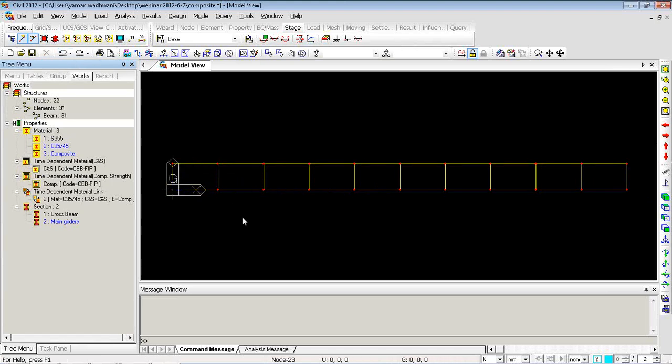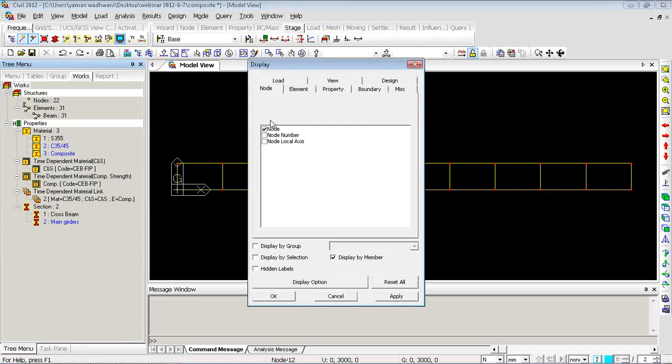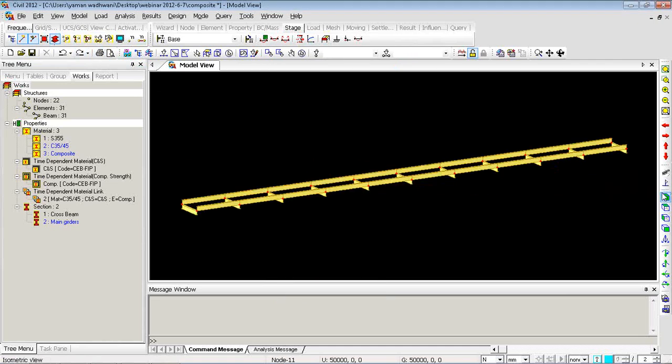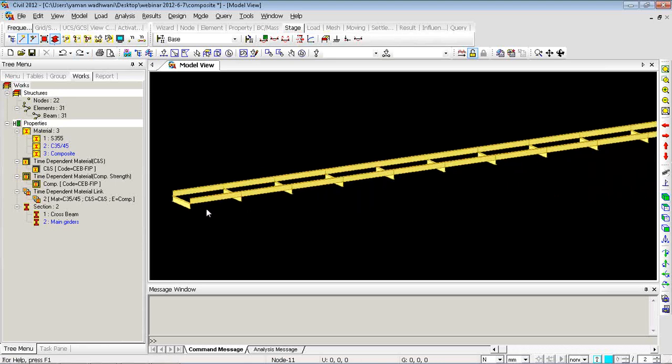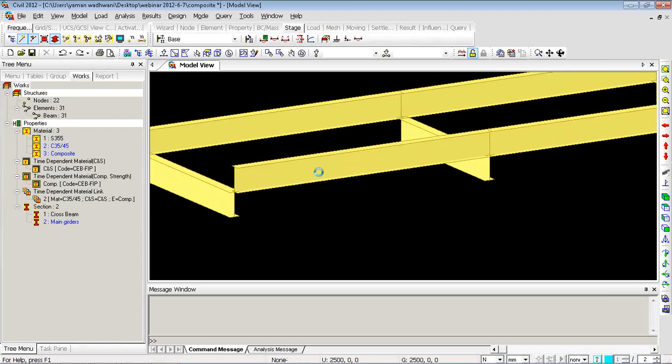I only want two girders, as I entered the section properties for two girders. This view, this XY, shows the global XY coordinates. Let's undisplay it for a better view. Okay, now it is clear. And switch on the 3D view like this. So here we can see the center bottom which we defined for the cross beams, these are all inputted as cross beam sections. So center bottom, you can see that the bottom is connected, or everywhere the bottom of the section is used for the element.